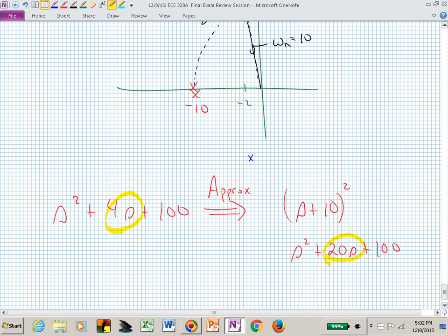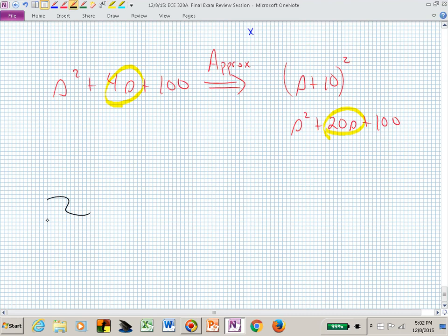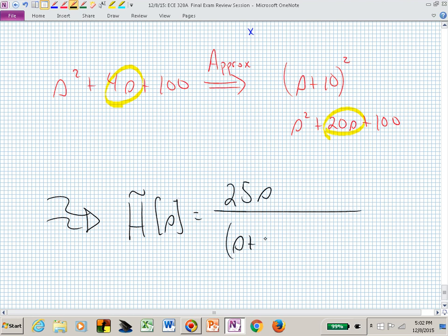They were almost on the imaginary axis, and we slid them all the way around to look real in our approximation instead of leaving them as purely imaginary or very close to imaginary. So this would be a very gross approximation, but we're okay with that, which means that instead of sketching the Bode plot of the original H of s, now we have this new H of s, which is 25s over s plus 0.5 times s plus 10 quantity squared.